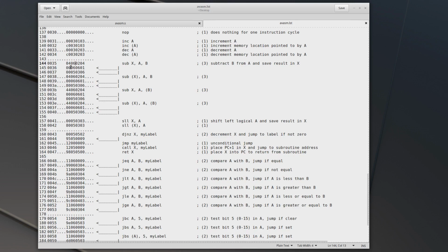The next instruction, 00, is an add opcode. And here we're adding register 6, which is our new intermediate value, with the register 1. Register 1, remember, is the other predefined register and contains the value 1. So here we're incrementing register 6 by adding 1 to it and storing the result back in register 6. So register 6 now contains the exclusive ORed and incremented register B. In other words, the 2's complement of register B.